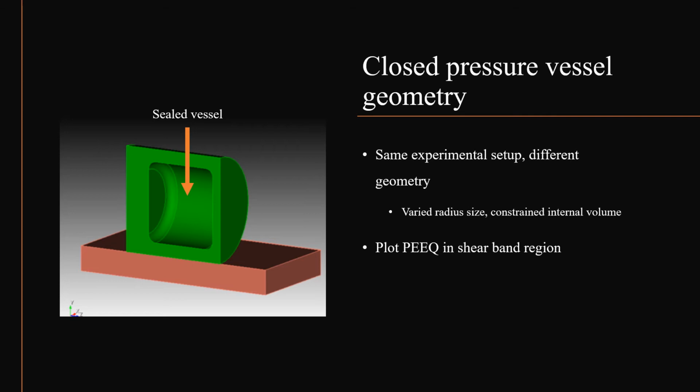Once this was confirmed, I began varying the internal radius size with the goal of reducing the maximum strain in the lower two corners. The two radius sizes that I chose, 1.69 and 2.4, were based on predefined internal volume limitations associated with the model. To compare the strain levels reached with each radius size, I plotted the strain in two elements over time, one on the left lower corner and one on the right.